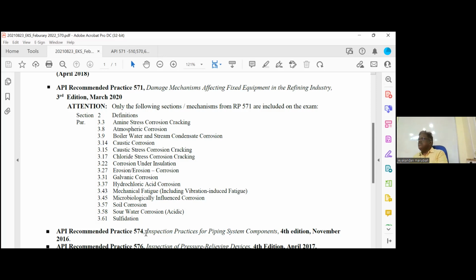The second group is surface cracks. Which type of cracks will come on the surface? All fatigue cracks are surface cracks. So first you should know what is meant by fatigue. Fatigue means cyclic loading. I told you there is one word, integrity operating window. Suppose your operating pressure is 100 psi; a small range is allowed to fluctuate.